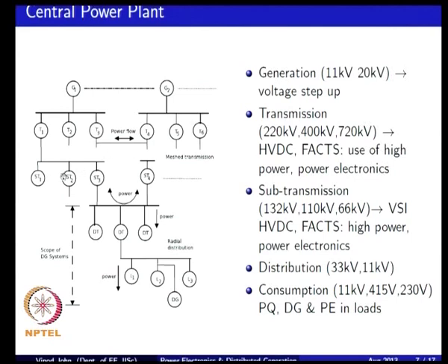They would be connected to the subtransmission or the transmission level. So, the wind energy needn't be distributed generation. Similarly, if you look at some of the newer solar power plants, they are rated at tens of megawatts, especially at the larger range. So, they can be considered as more like centralized generation rather than distributed generation.